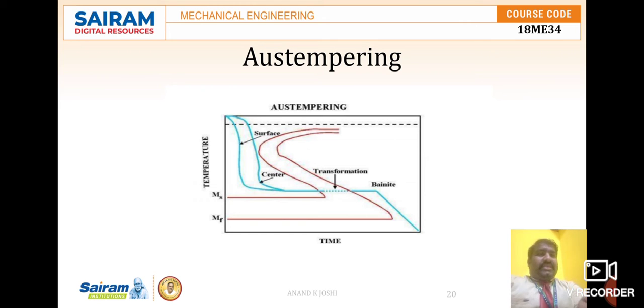So here we can see that austenite and martensite will be there in this space, and this will be austenite and martensite on this path, okay, the complete path. So this is what we call surface sampling. This blue color indicates the surface sampling, and this is air cooling. This is bainite, and after that, at this corner, the blue line ends with the air cooling. So this will be drawn on a temperature-time curve graph.